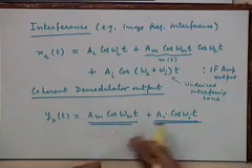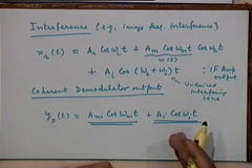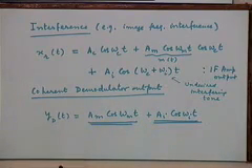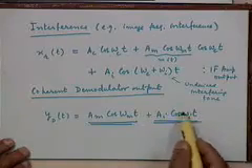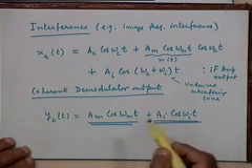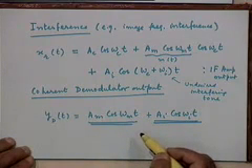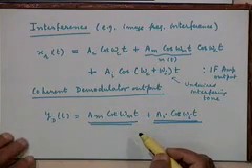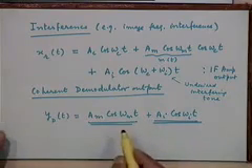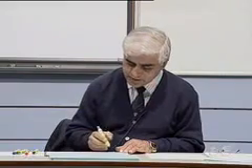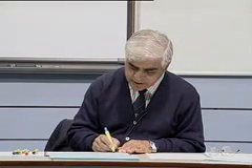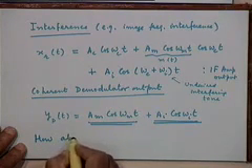We call this a graceful behavior. The output is as bad or as good as the input. Let's put it that way. Input is bad, your output is bad. We can't do very much about it. So the output interfering component is directly proportional to the input interfering component, right? So that's what the coherent demodulator will do. Now how about the envelope detector?